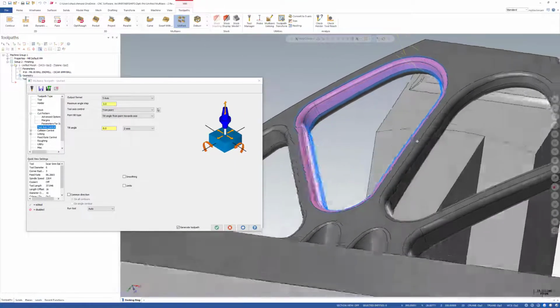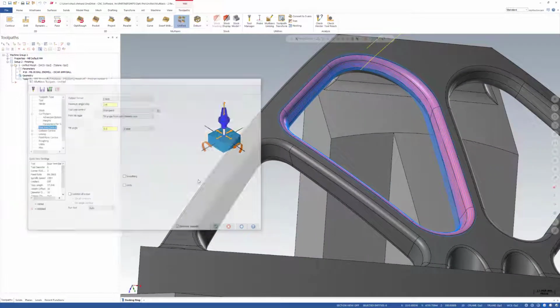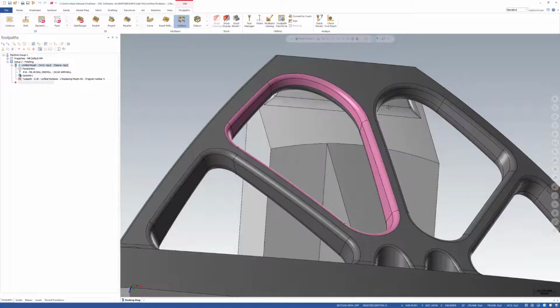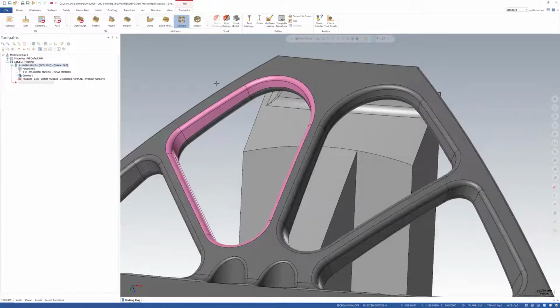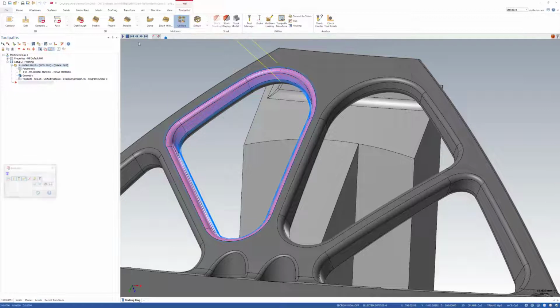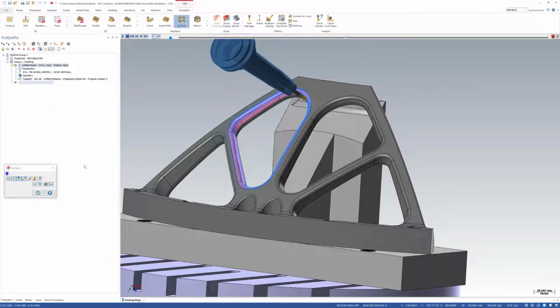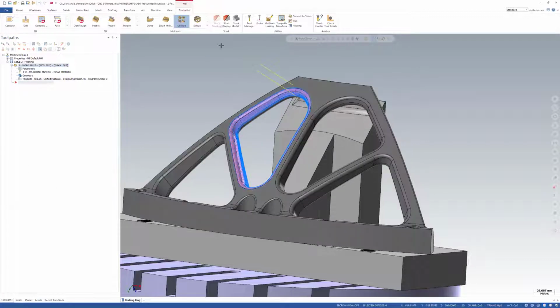I can see there is our morph toolpath. Right, looks exactly like you'd expect. Click OK. That was a preview though, so now we're going to generate this toolpath again because I had the Generate Toolpath checkbox active. If we backplot this, we can see there is a nice morph toolpath. So replicating morph is extremely easy, but I do want to show you some new things that we can do in 2023 using unified. So let's build a new one.